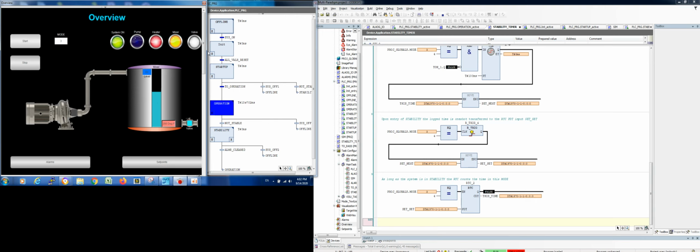You see the valve came on there, and it constantly drains the tank. The pump comes on when the level is below 20%. Tank level is below 20% for 5 seconds. So it's showing your mode there.